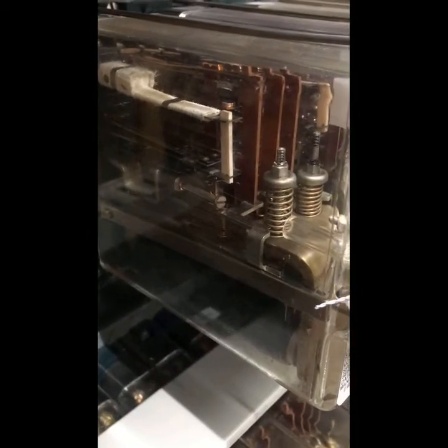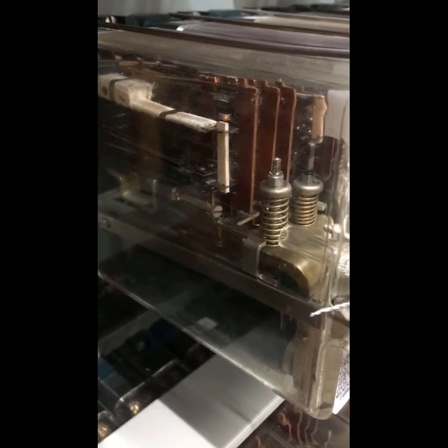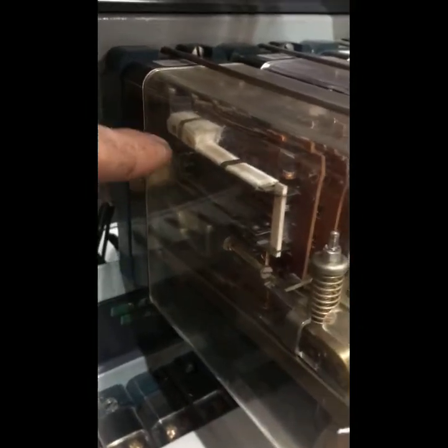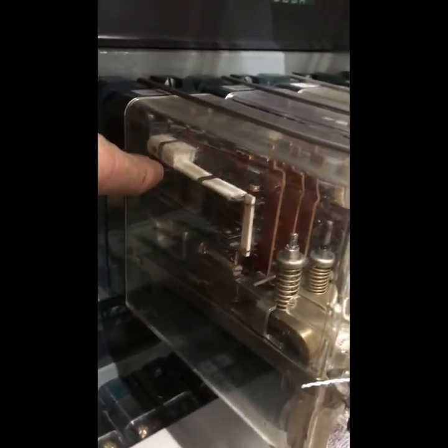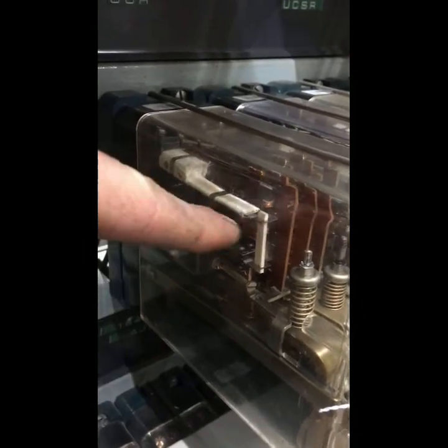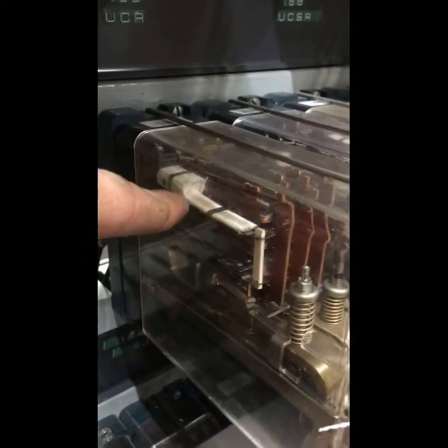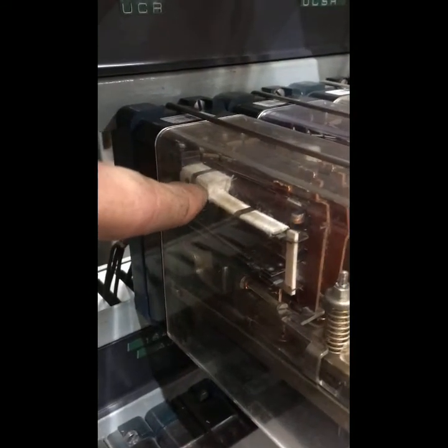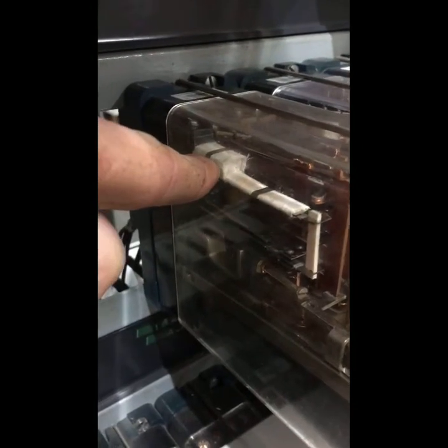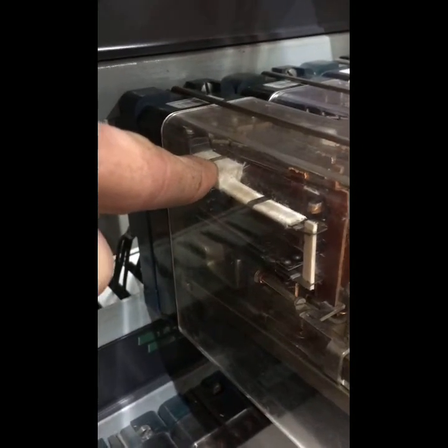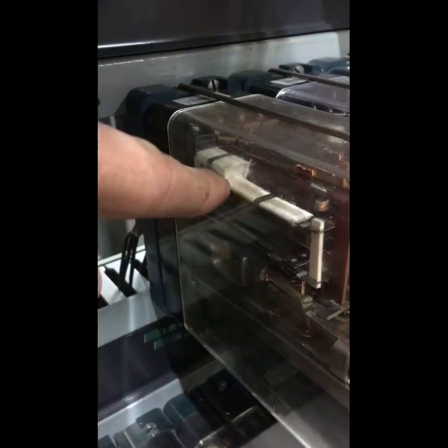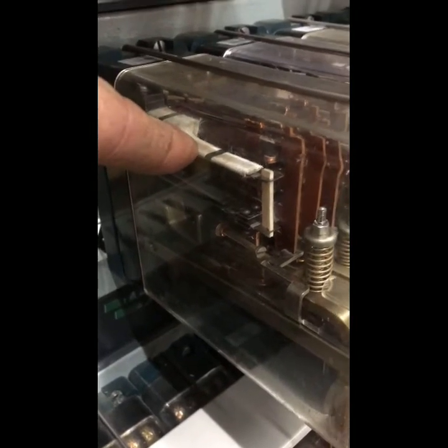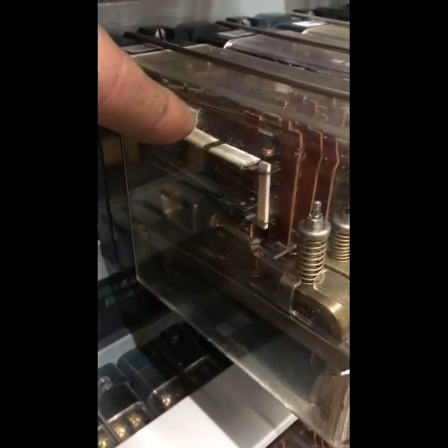I'm going to briefly mention approach locking and the timer relays that we're going to use here. These are thermal element timer relays. What you have in here is a bimetallic strip, and there's two of them. As you apply an electric current to the bimetallic strip, the differential between the top bimetallic strip and the bottom bimetallic strip, which are bonded together, causes one to heat up faster than the other, thereby bending the strip. It will act like a spring. Now, the thing about thermal element relays or timer relays of any kind, there is what is known as hot and cold proving.